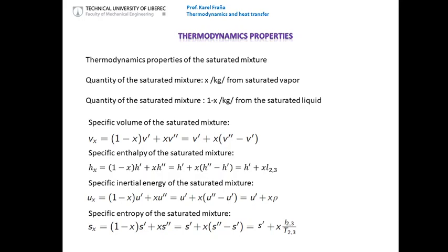So it's a very simple calculation. All you need to know is the specific volume of the saturated gas and of the saturated liquid. And this information you can find in tables or in the graphs. And I can show you later. The same is possible if you look at the specific enthalpy, the specific internal energy, or even the specific entropy.